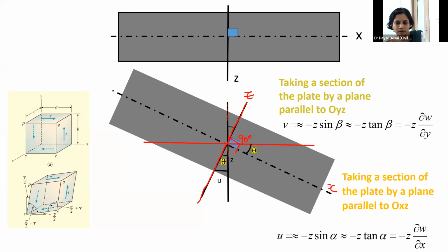Now, the significance of this: you have studied shear strain. The definition of shear strain is, just like it is shown here in the second image, that if this is 90 degrees and you apply any shear stress, these two sides will distort to less than 90 degrees.